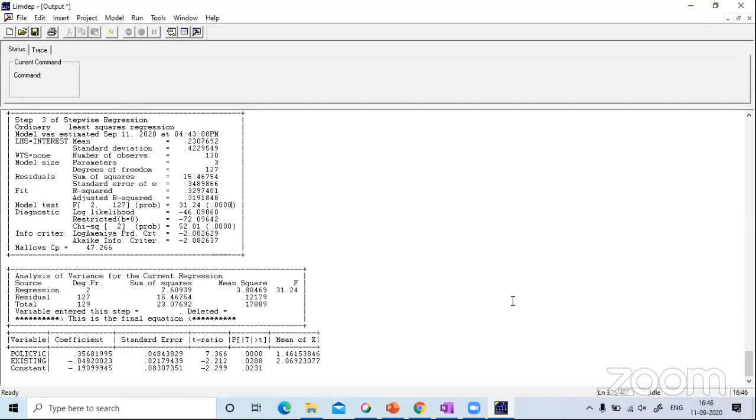When it comes to a huge set of data, the software gives better performance. If you have many variables xn as well as many data points, here we have considered only 130 samples, which is very few. In transportation planning, a minimum of 300 samples is sufficient with respect to household size. But for planning and other modeling aspects, we usually consider a minimum of 600 samples. If you are going for an SEM model, you need more than 1000 samples. With respect to the sample size, your significant values are highly influenced, and accordingly you will get a better fit in your model development.